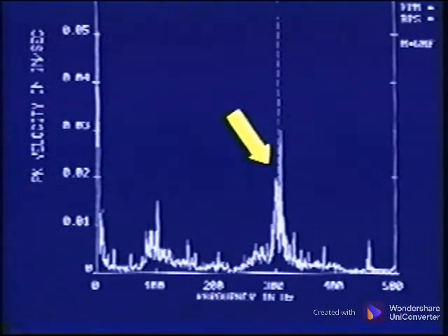The peak at 304 Hz is the gear mesh frequency, and the side bands are spaced at 1 times turning speed of the shaft. The energy in the area of 100 Hz is the resonant frequency of the gear. This is a typical example of gear wear. When gears wear, the surfaces tend to strike as they mesh, exciting the natural frequency of the gear.